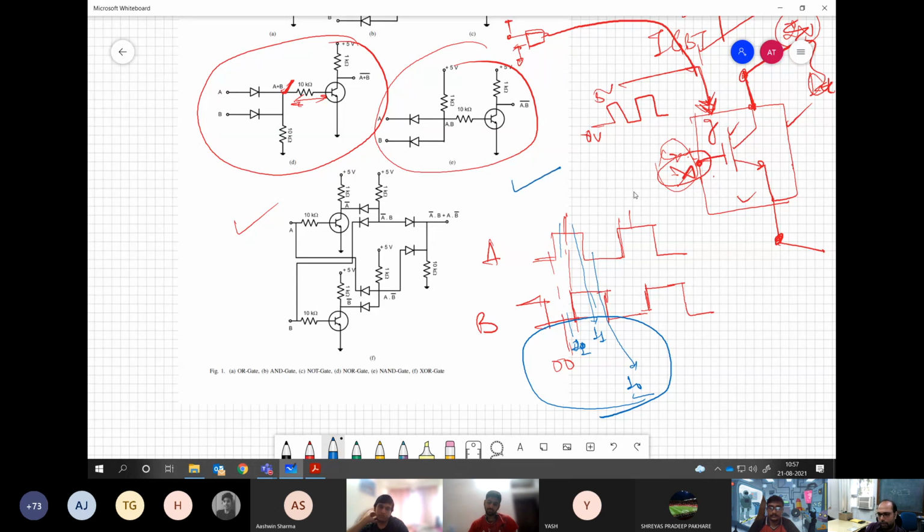Otherwise you need to stop the simulation every time, change the logic, then check again. This kind of exercise, don't do. When you are making it, give it properly so that all possible inputs are generated automatically, and so you get all possible outputs. You need not run the simulation for 10 seconds or something like that. You can take a sufficient frequency, let's say some 100 Hertz or more, and you can test this complete thing in, let us say, 0.1 seconds or something.